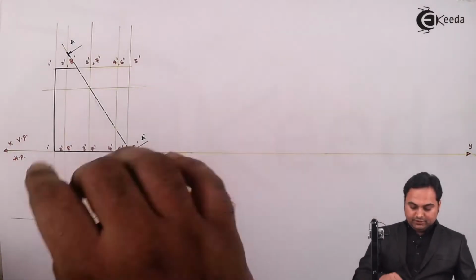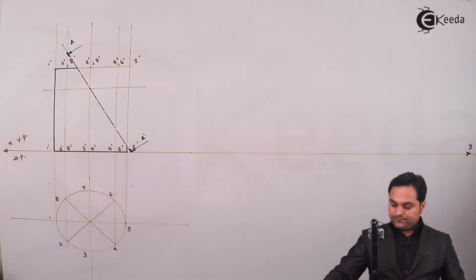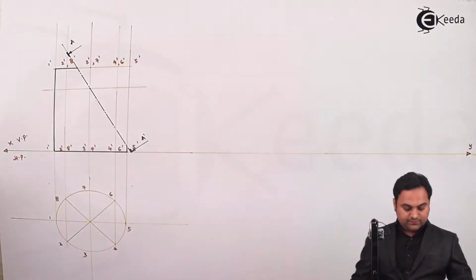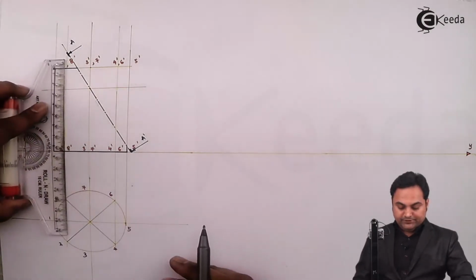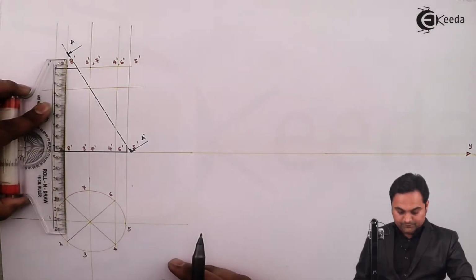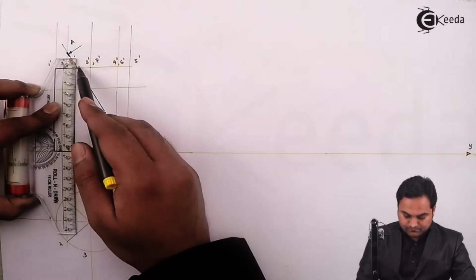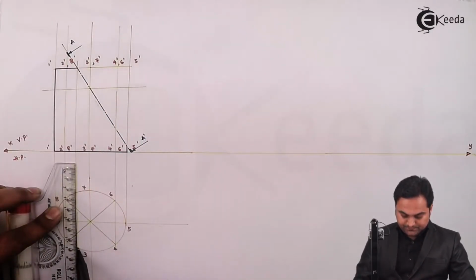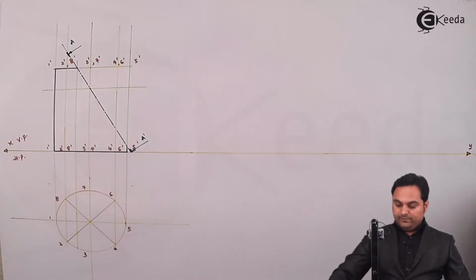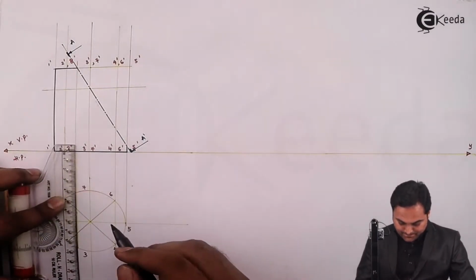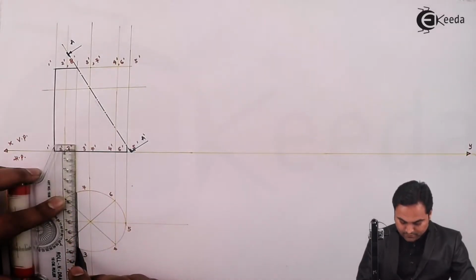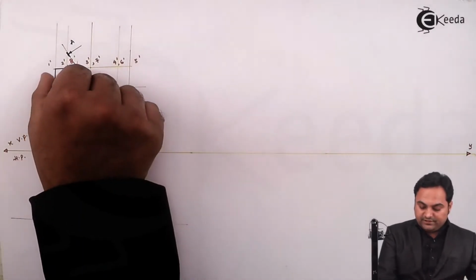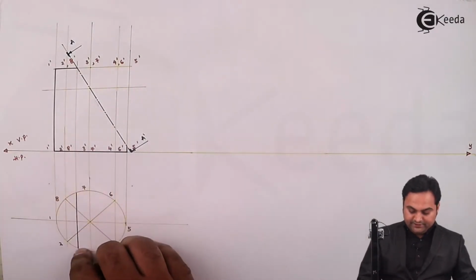Next, in the top view, when we are looking here, the cylinder is being cut at this location. So when I project this point in the top view, here I am going to get a line, and that line will be dark, and whatever portion is there on the left hand side of this line, this much portion will be retained.